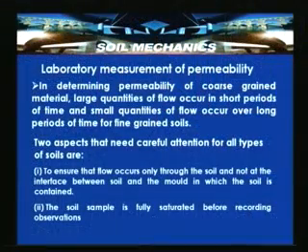Let us discuss the two laboratory methods called the constant head test and the variable head test or falling head test for determining the permeability in the laboratory. And indirectly, for typically clean sands or mixtures of silt and sand to some extent, determining the permeability by using a correlation between an effective particle size and coefficient of permeability is very useful in estimating the permeability value. Before looking into the laboratory measurement of the permeability, two important aspects have to be understood and ensured.